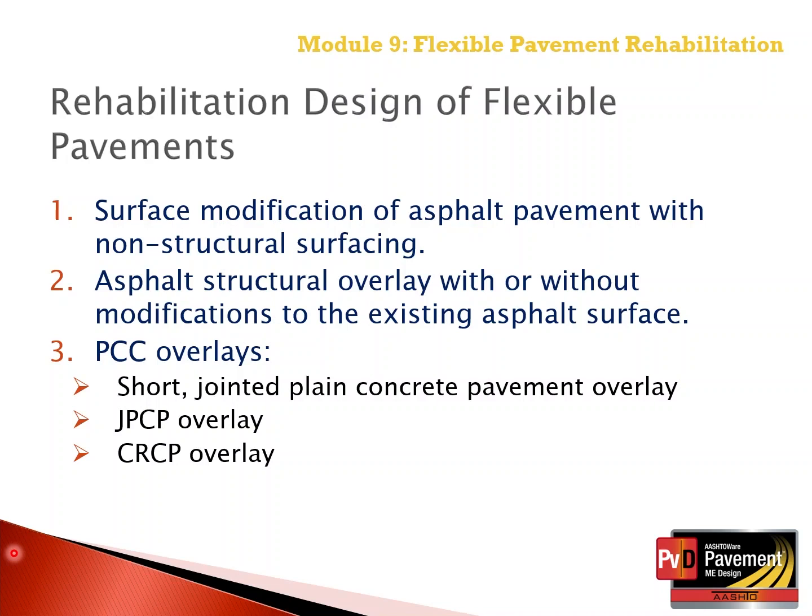As noted earlier within Module 9, the rehabilitation strategies and design of flexible pavements are grouped into three different areas. The first, surface modification of asphalt pavement with non-structural overlays. Second, asphalt structural overlays with or without modifications to the existing surface. And finally, concrete overlays themselves. So we will go through each one separately.